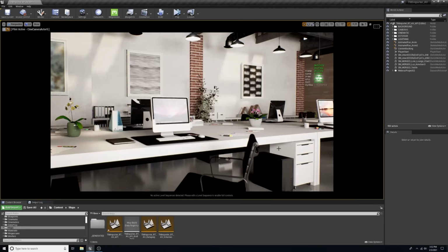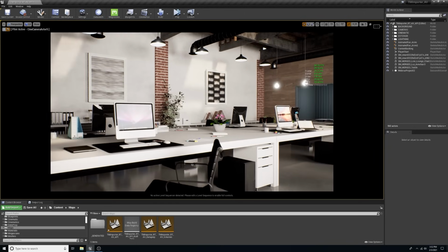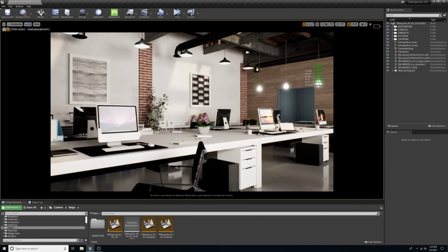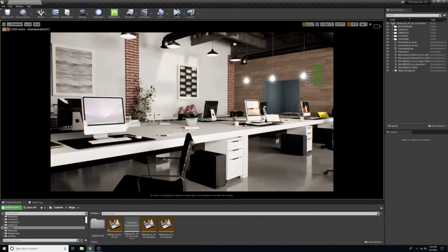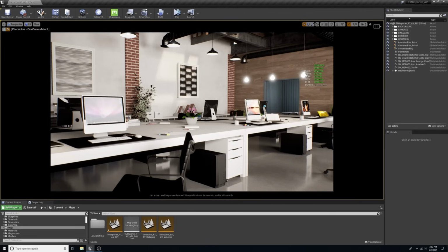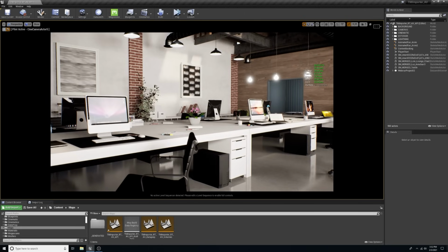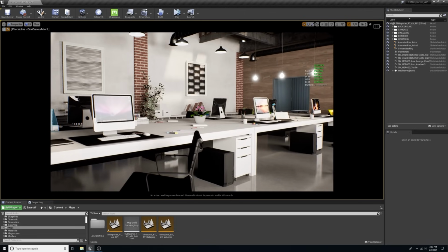To do this, I'm going to switch scenes. So the Remote Control API is going to allow you to make changes without having to filter through the settings in the Unreal window. So say you have a client or someone in your office who would like to make changes but is not well versed in Unreal. With some initial setup of settings that you would like to make accessible, the person can connect to the local host and make those changes through a web browser on their computer or phone.